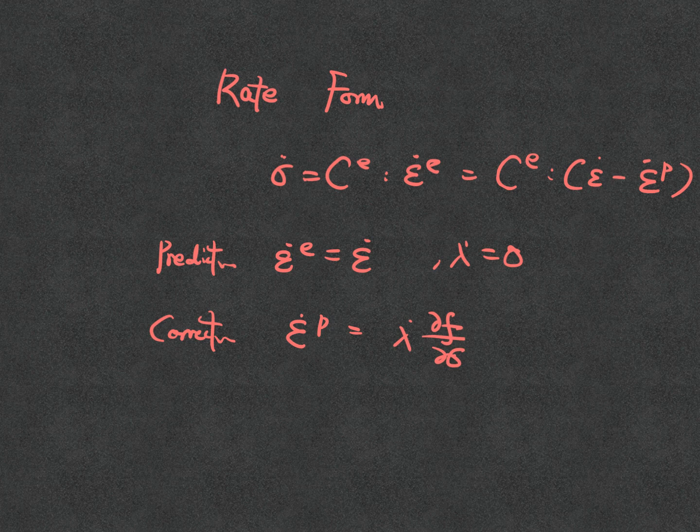So what happens in finite deformations is the following. I will still have the same form, but instead I want to introduce a relationship. I will first write the energy as a function of the left Cauchy-Green tensor. This is called the energy functional, or the elastic stored energy.